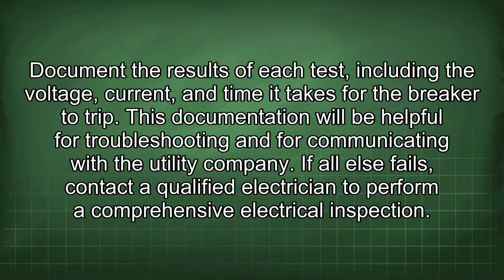Document the results of each test, including the voltage, current, and time it takes for the breaker to trip. This documentation will be helpful for troubleshooting and for communicating with the utility company.